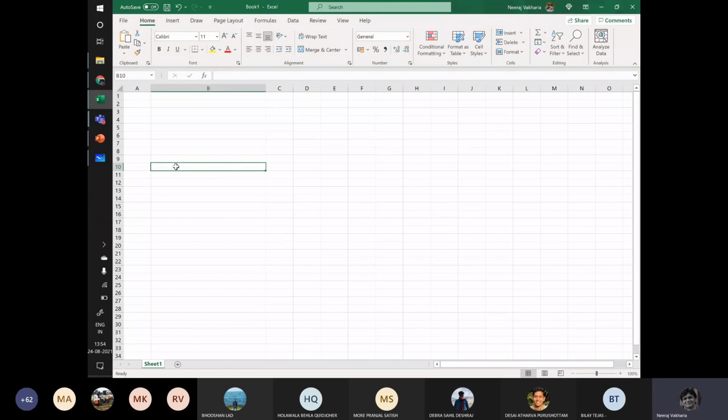So here, if I am writing for north side, consider this as a measurement sheet. If I am writing here north side wall, or maybe living room wall, whatever is easier for you to refer with the drawing. Now you have here length, you have breadth, you have depth. Here you have total volume. Rate, remark, this all will come as per what you have received for the measurement sheet.